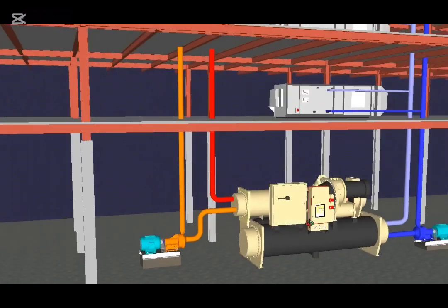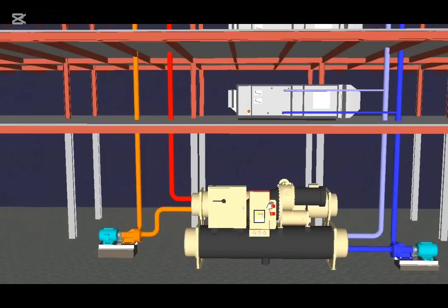And yeah, so this is where the condenser water then comes back into here, enters into these coils inside and picks up more heat, and is sent back up to the cooling towers. It's important to note that this system here, the condenser water system and the chilled water system, are completely separated.